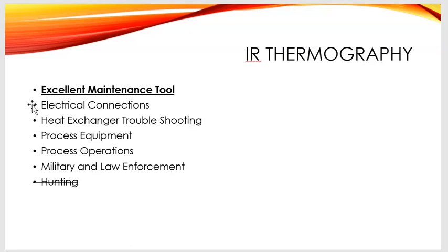So you can scan the equipment with your infrared, see that there's a connection getting loose, shut the electrical source off, go in, clean up and retighten that connection, put it back, and it doesn't continue to get loose until it arcs across and explodes the connection that's going into it. I've seen a lot of serious injuries through that over the days, and the infrared inspection has really been a good source of correcting that.